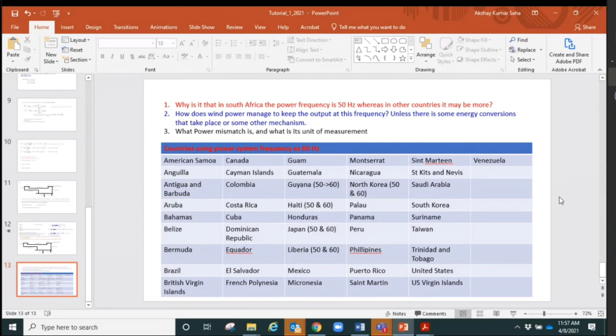As you increase the reactive power, keeping the active power, we're not talking about active power at the moment, we're only talking about reactive power. As you increase the reactive power, the MVA power supplied needs to be compared with the MVA rating of the generator. So that is another part. Right, so all those things will come into the scenario.